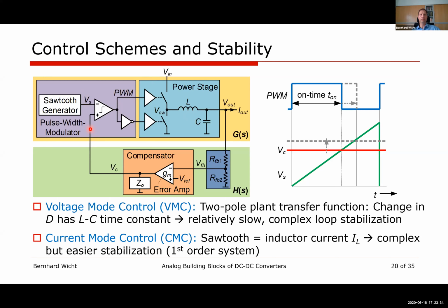That's the point. So it does not replace the voltage feedback, it complements that system? Right. The voltage feedback actually remains. We just add a second control loop, which is usually scary, right? A second loop. But in this case, it's really nice to handle because with the loop dynamics, the inner loop disappears and the outer loop remains. That's the one that really helps us to control in a similar way as in the voltage mode control. Thank you.